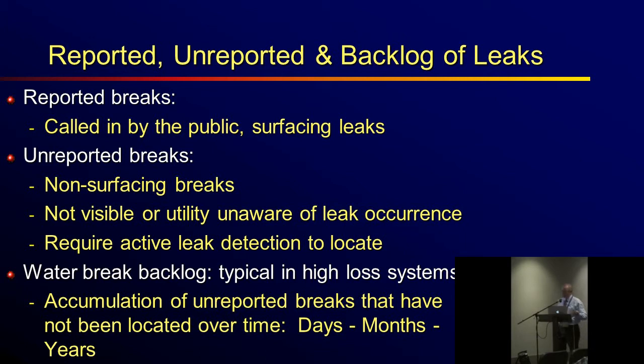I just mentioned a moment ago the water leakage backlog is typically high in high loss systems. There's a lot of it. If you don't do a proper water balance, you really haven't defined how much is in there. And that's why it's so important, in the fundamentals, to get a standard water balance to determine the amount of real losses in your system. It's an accumulation of unreported leaks that have not been located over time, days, months, or years. Years of running at high flow rates.